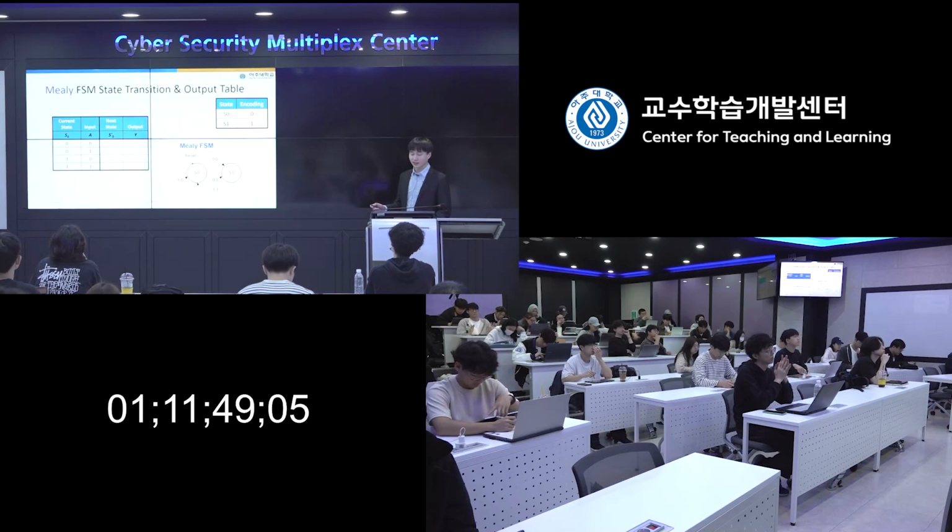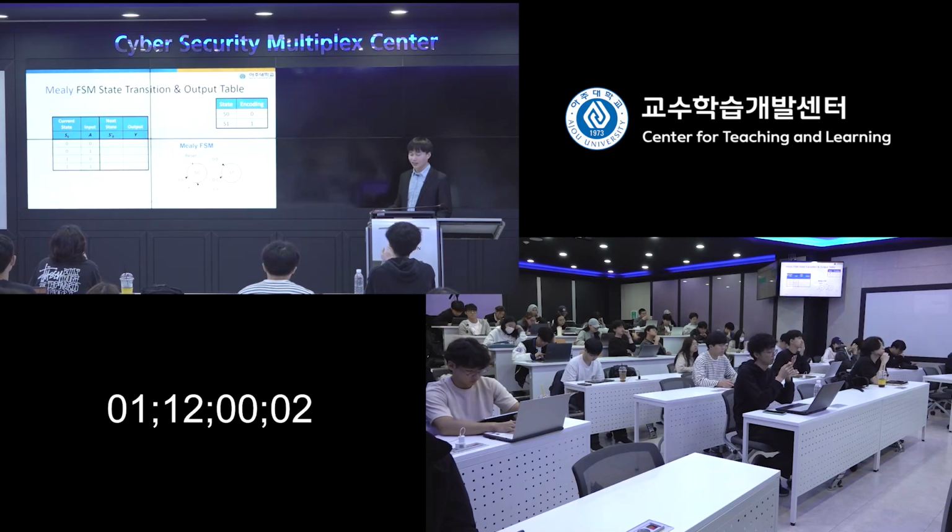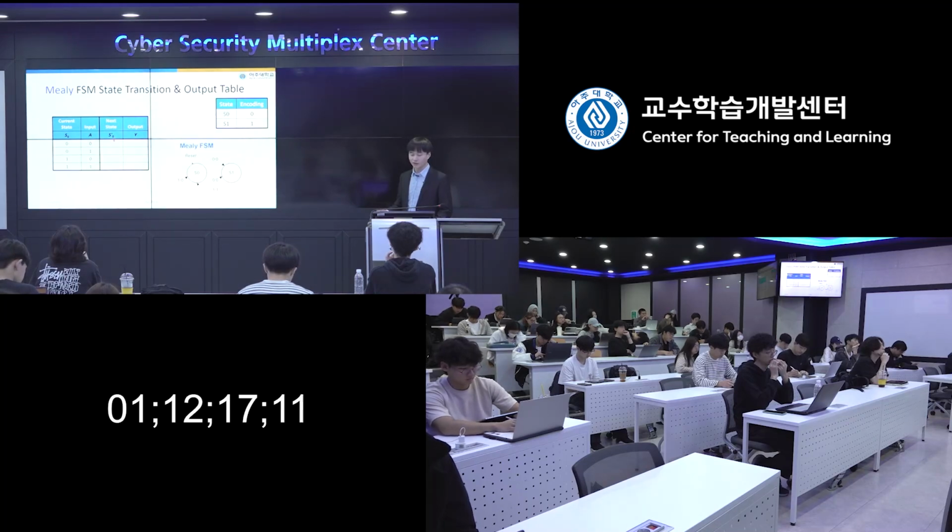The next state is from 0 to 1, for example here. S0 has 2 outgoing arcs, so the next state will be either itself or S1, either 0 or 1. It depends on the input. If the input is 1, then it will be 0. If the input A is 0, then it will be 1. So in this style, you can fill it out, right?